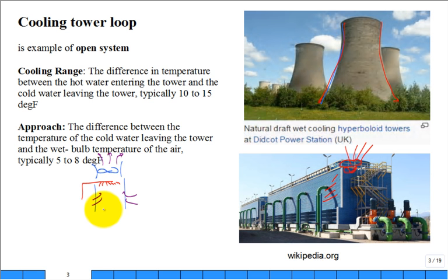It came from the heat of the liquid. Some of the liquid went away, it vaporized, evaporated, but some of the liquid is collected at the basin. That liquid's collected in the basin, and then it continues on. So you always have makeup water in a cooling tower because that's how it's providing cooling to the water. It's evaporating some of it.